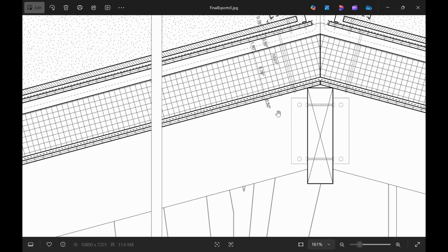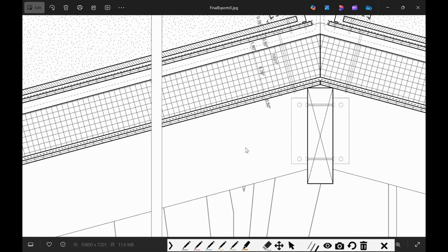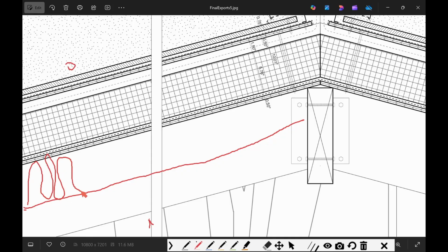Some people want to insulate the roof as well with cavities. Some people don't. They want to expose the roof structure. If they have really nice structural elements for the roof, they want to expose it. Other people want to mitigate as much sound as possible. The other reason some people want to insulate is that it limits the temperature differential between outside and inside. So maybe they'll insulate half of it, so part of the structure is poking out, and this is insulated as well.